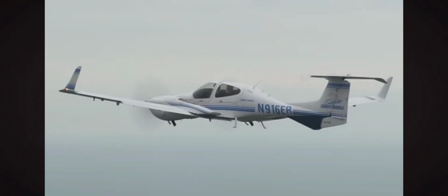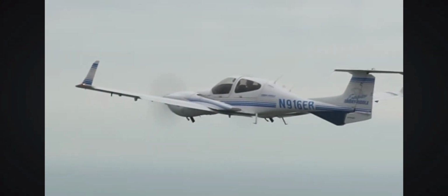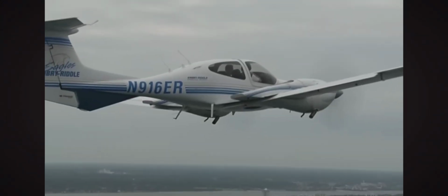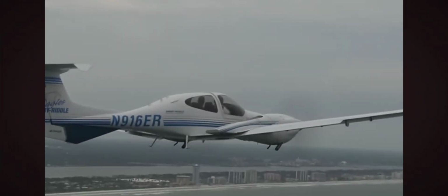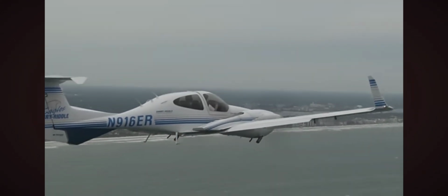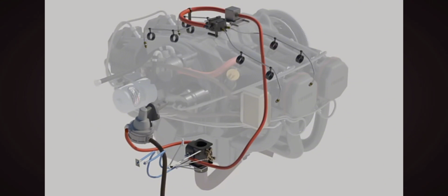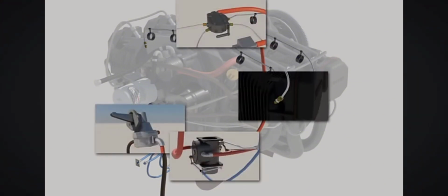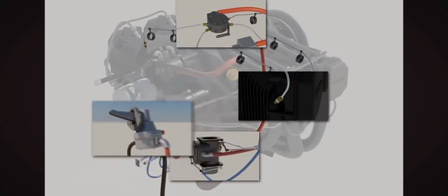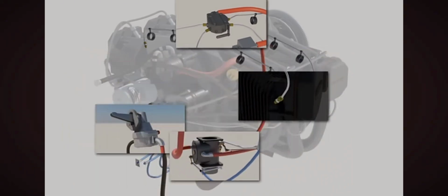which have many benefits over carbureted engines. Fuel injection engines reduce the amount of fuel required, increase engine power output, and allow for the precise use of the fuel. Rather than having a carburetor, a fuel-injected system is split up into different components. These consist of fuel pumps, a fuel control unit, a fuel manifold valve, and finally, fuel discharge nozzles.